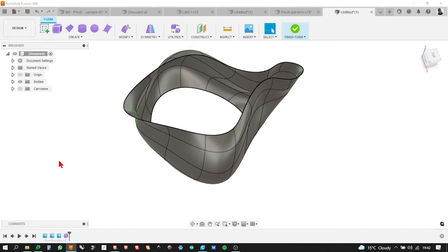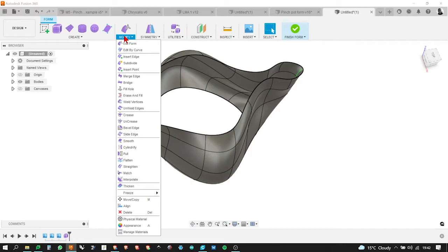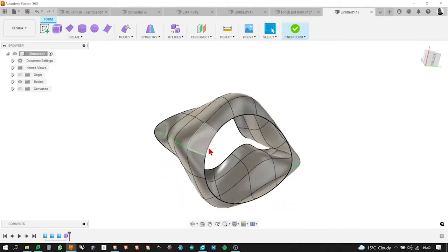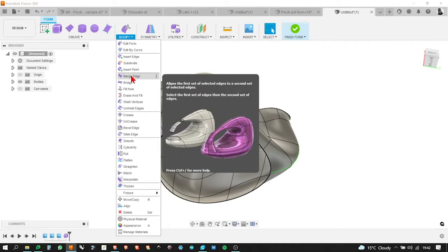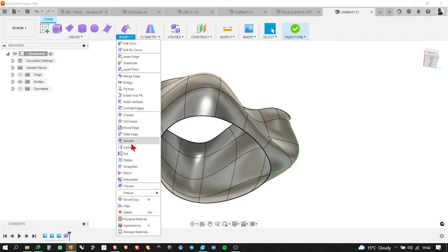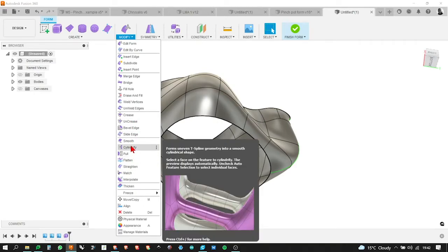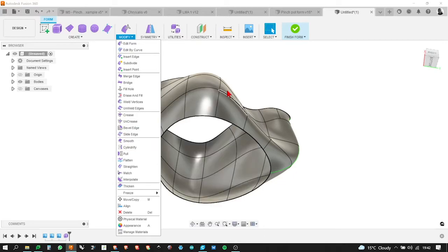Okay, so it's a bit different in the sculpted environment to the surface environment. This is a surface, we could just patch it, and we could take this out into the surface environment and patch it, but I'm not going to at this stage because we can fill holes within the sculpted environment. So if you went into the other sketch mode, you would put a circle in the bottom, and then you could probably use the stitch or something like that. You may be able to bring something in to merge an edge. I'd have to look at that, I have to say, where you could perhaps snap something to a circular shape. Don't know, I'd have to have a look.